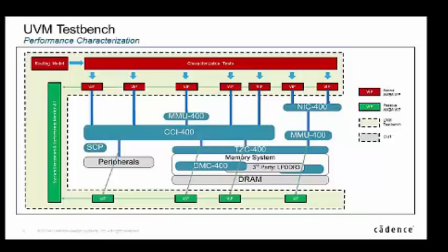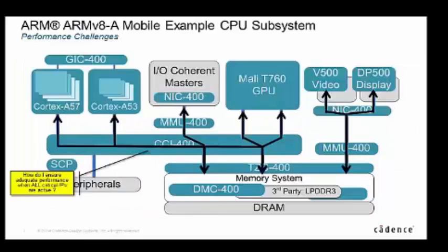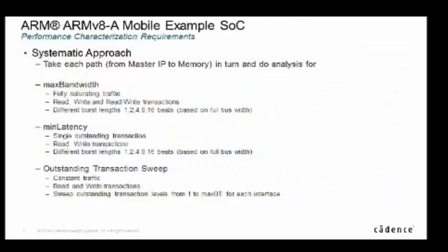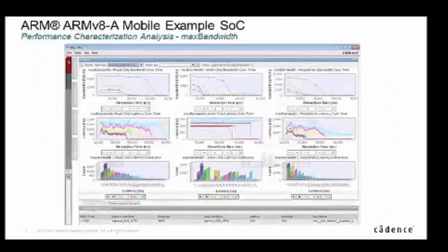So you would say, here's a master, it's got this bandwidth requirement. Once you've done that, and if you're satisfied with that, you could even go to the sophistication of building in UVM sequences that will actually make it a dynamic use case. So IPs can fire up and use some performance of the system and then go to sleep. And that's what we would call kind of full use case.